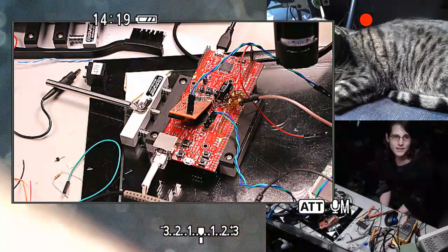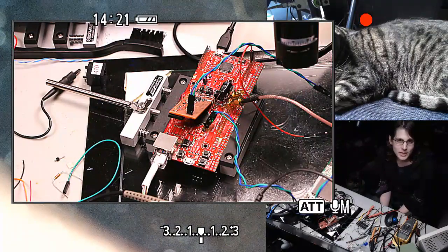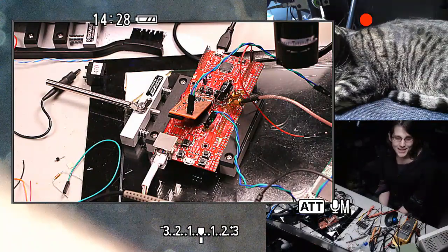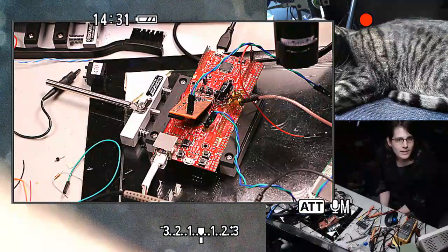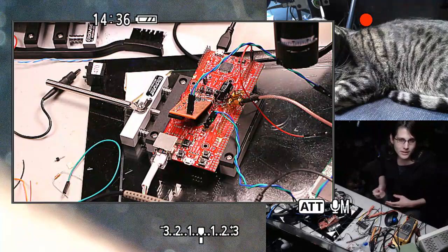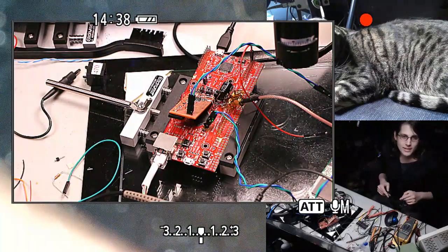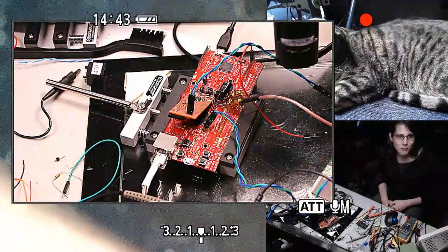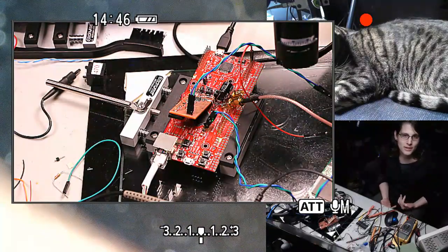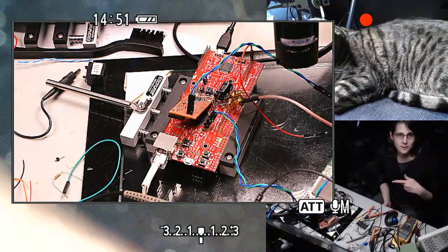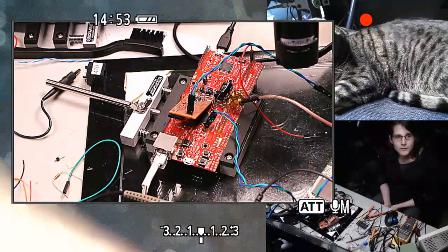So maybe one other solution is to find some Ethernet chip made by TI that probably uses the same IP core and probably behaves the same way. But I think the easiest thing to do, since I have a couple of these boards handy, is to write some firmware on here that just acts as a packet bridge. Ideally it would just hard code the link status, assume it's always a 10BASE-T full duplex link that's always present, and then forward packets between some other port that I can interface to the outside world and the other device I'm working on getting the firmware out of.